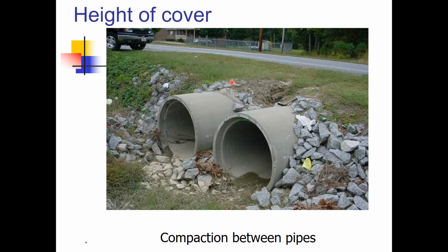Should have a head wall. Compacting between pipes is difficult. One pipe always seems to silt in. LMS would have been a better choice. There will be erosion control issues. Box culvert would be better. Be worried the rock may crack the pipe. Driving hazard. Need a head wall with a wing wall. Not much cover. Use elliptical. Twins don't flow well. Kids crawling in pipes.